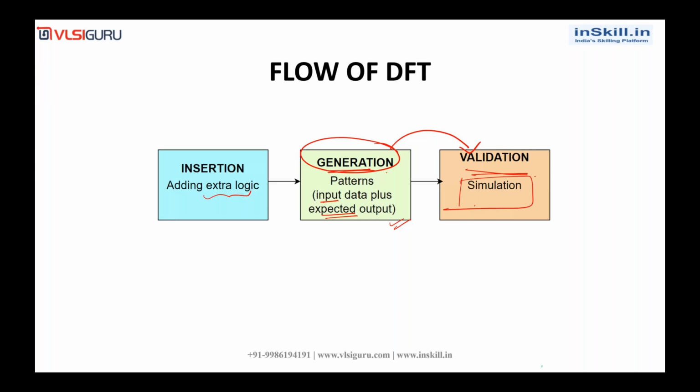So this is the flow of DFT. First we have insertion, where we add extra logic like scan insertion, EDT insertion, MBIST insertion, and boundary scan insertion. Generation means generating the test patterns. And validation means validating the generated patterns with the help of simulations.